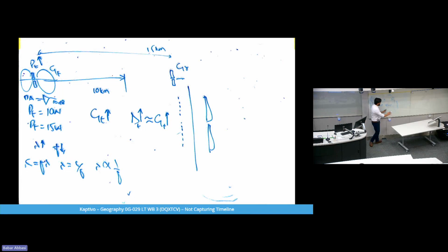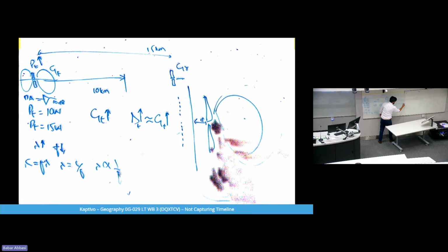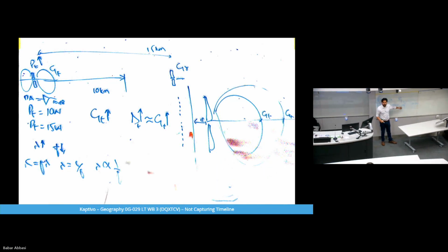So these two elements, if this distance is carefully chosen, then this previous antenna was radiating like this. Because of this mirror effect, it will radiate like this. So my gain GT has increased by this mirror effect. Okay, so it's an excellent solution. So that's why you might have seen reflectors behind antennas.